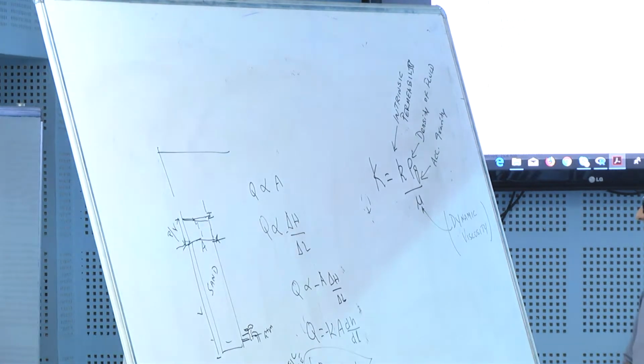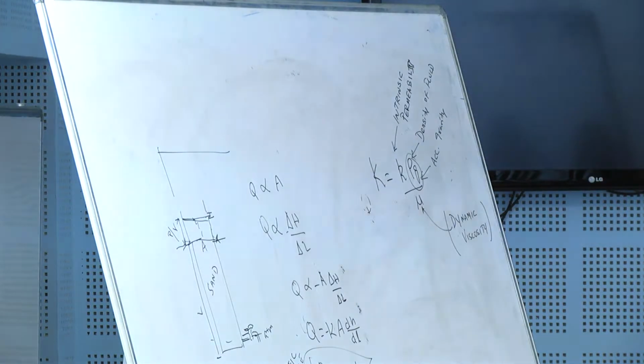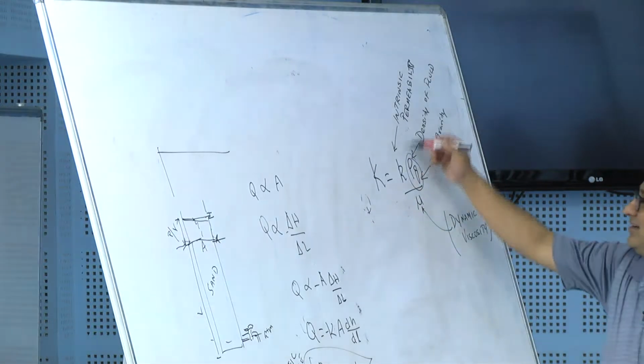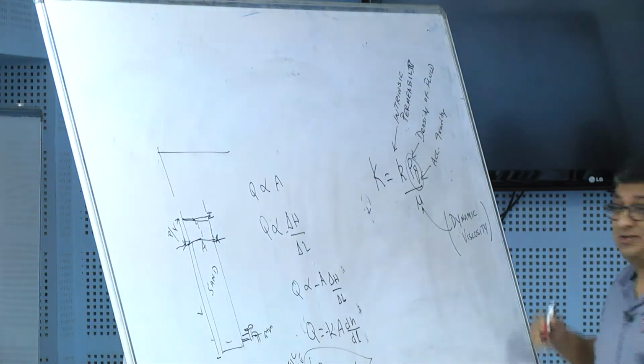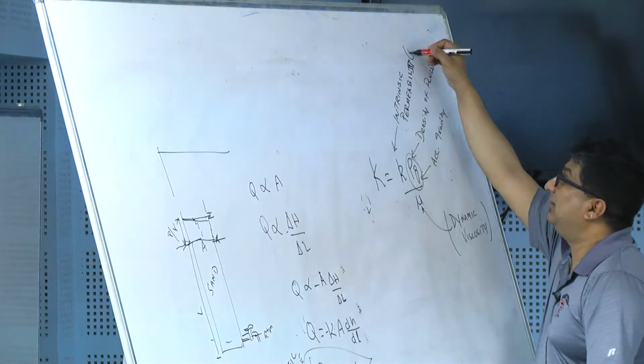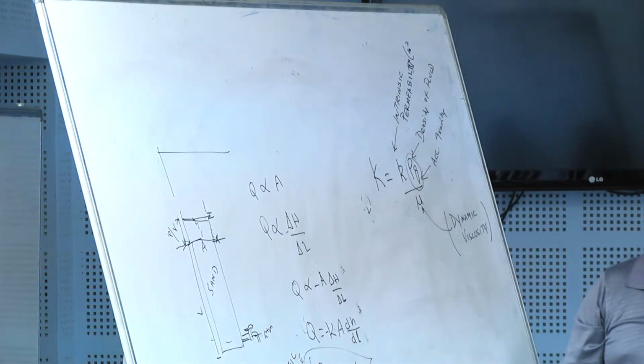Think about it, okay? So this rho g term is also called what? Specific weight, okay? It's specific gravity if I divide it by density of water. So if it's anything, it's just specific weight. And if I take this mu divided by specific weight, I get what? I get the kinematic viscosity, okay? So you can write it. But this intrinsic permeability is measured in meters squared or centimeters squared or whatnot.